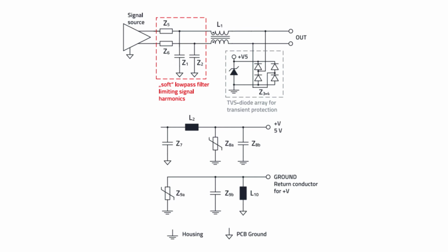Next, we're going to talk about the USB 2.0 interface, and this is a widely used interface for data and power transfer between electronic devices. It provides a signal bandwidth of approximately 240 megahertz and an impedance of 90 ohms. A typical power supply for USB 2.0 is 5 volts with a max current of 1 amp. In regards to component selection for the USB 2.0 interface, we have a few steps we need to go through first.